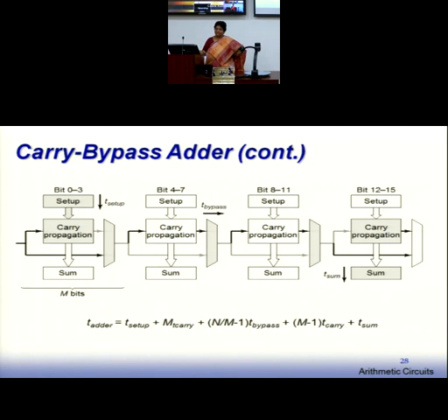Now you decide. Or you find out some analytical reasoning for that. This kind of architecture is called variable carry skip, where you are not uniformly sizing all the blocks. Rather, every block has a variable number of bits. How to have that, you can decide. Or you can find an analytical expression to find the best way of making the variability or the size of the block. So this is called a variable carry skip.